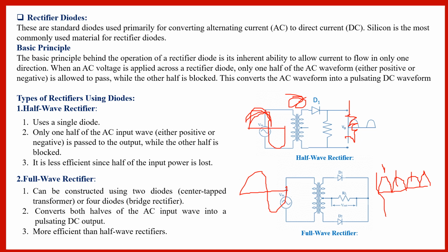If we see the advantages and disadvantages of half wave and full wave rectifiers, the disadvantage of the half wave rectifier is that the pulsating current in the load contains an alternating component whose basic frequency is equal to the supply frequency, as a result of which filtering is required to produce steady state current.